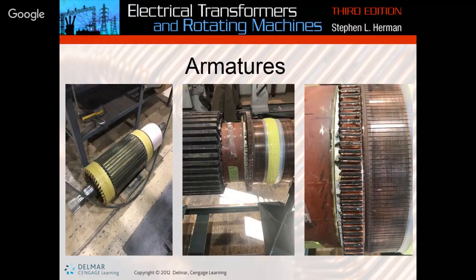So at every single point, basically, and how a brush works is a brush is usually going to, depending on the size, but most of the ones that I've seen, the brush is going to get set up to be able to conduct on 3 of these little lines. That's what our goal was, to get the brush to make contact with 3 of these little lines at a time.